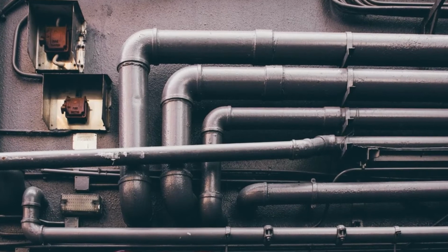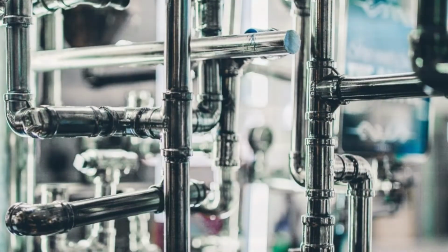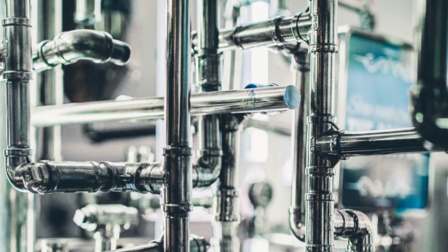On a similar vein, number 6, do the same thing with the plumbing layout. If the plumbing layout is optimized, there's less piping. There's less heat given off by the hot water pipes. There's less equipment required to heat the hot water. Lower piping costs, lower equipment costs.